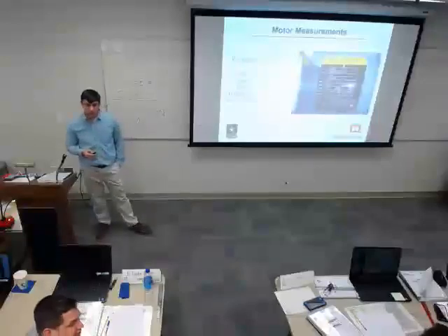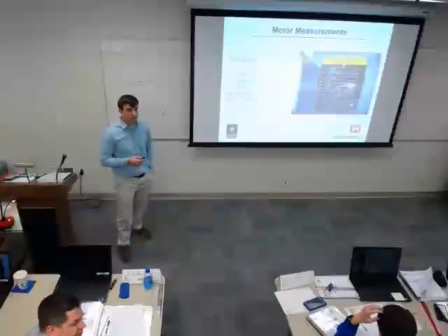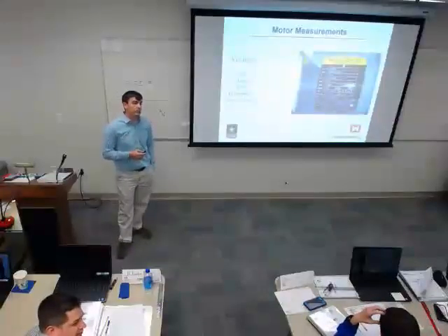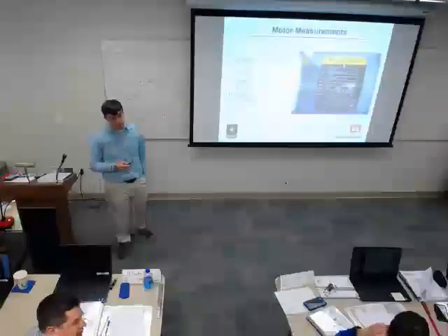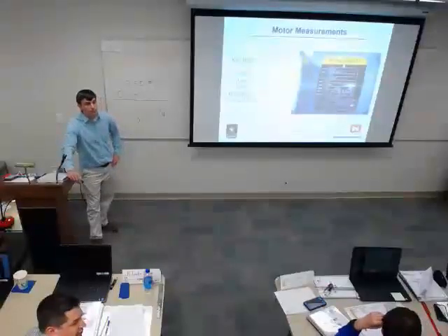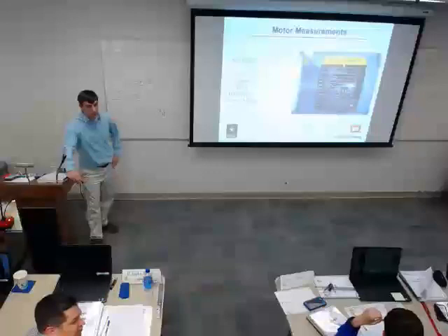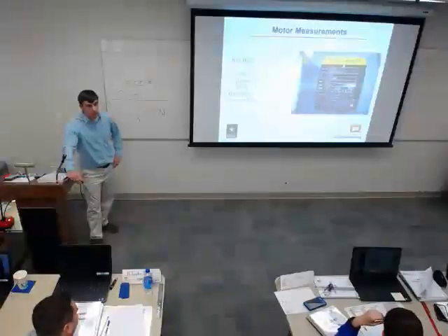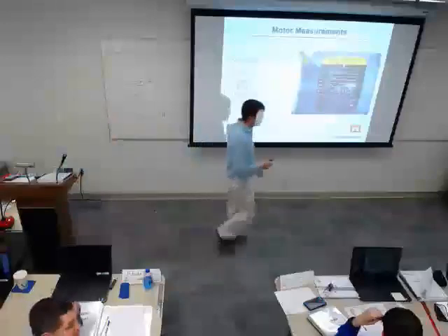And one of the things you need to watch, I think it's the amperage. I think it's a 5% difference we're okay with, or that motor life starts to go down pretty drastically. On new construction, that's something that might be addressed, might be a motor problem. On existing construction, if it's not a motor problem, you're probably stuck. But just be aware that's one of the things the TAB guys, again, just give you the average. You want to see all 3.